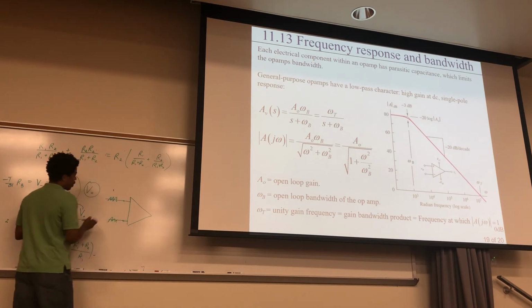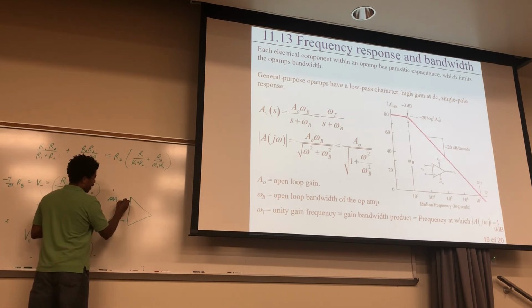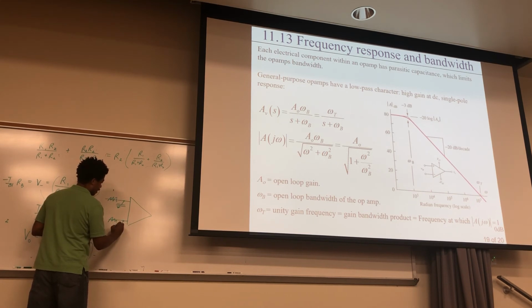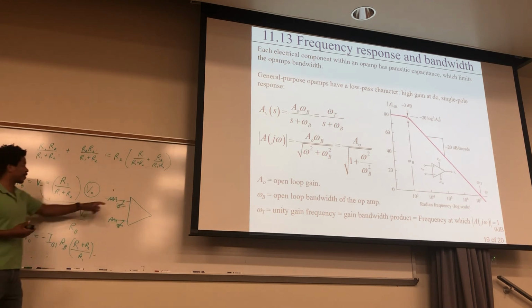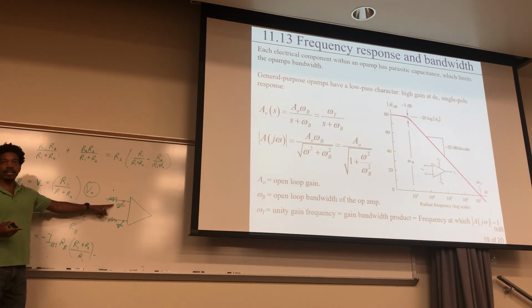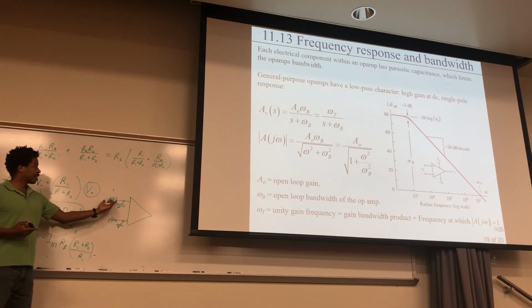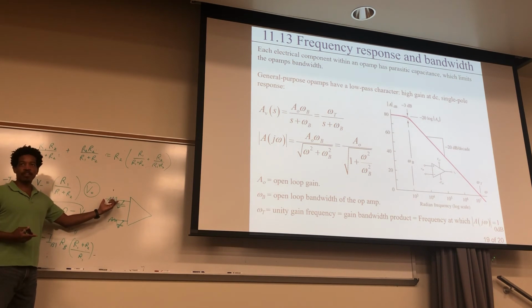All these components, you could think of it as there's a little bit of parasitic capacitance between this and ground, everywhere. The reason why is that even if you don't have an explicit capacitor, it's really there anyway, because you have these conductive parts, and they have fields, they're able to store charge, even though it's a very little bit.